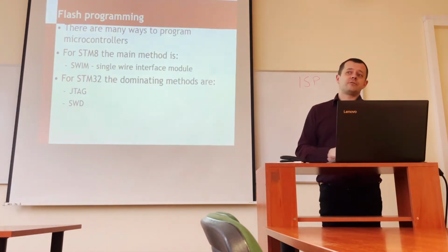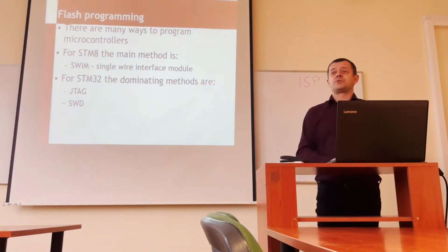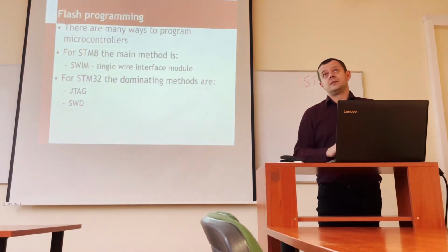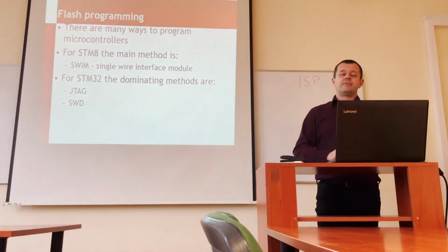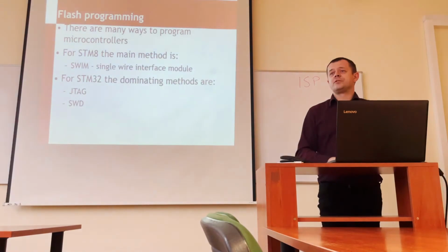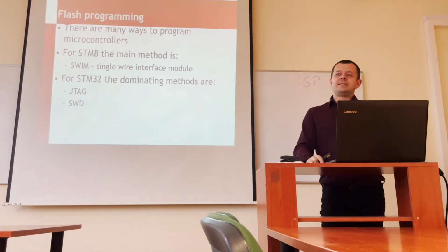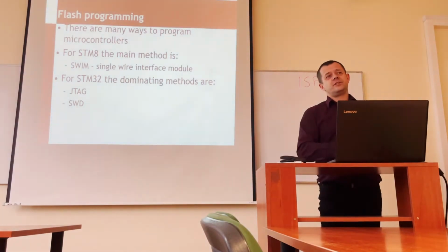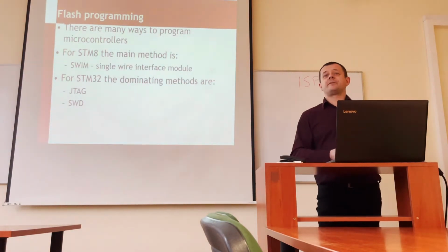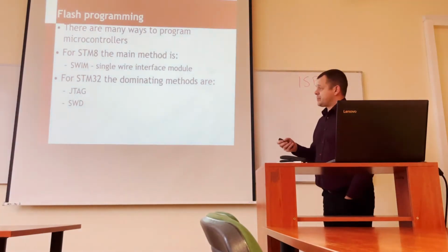Today it's possible to program microcontrollers over USB, which is also very nice. We can program, for example, the STM8, not really, at least I don't know, maybe the very newest one. I'm not tracking the STM8 market closely. But with STM32s, for example, you can switch into UART programmability mode, then switch into this boot mode with USB, connect the USB cable, and here it is, it's enough. Then you can program it directly through the USB. But that's for programming.